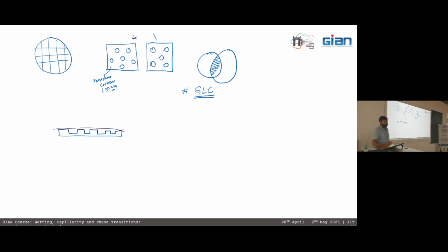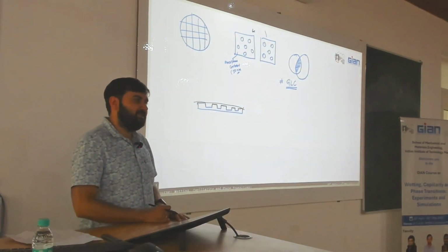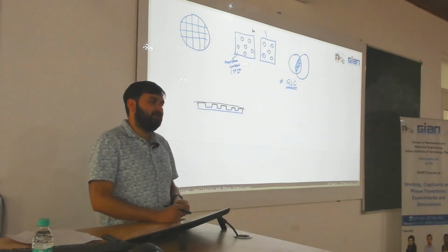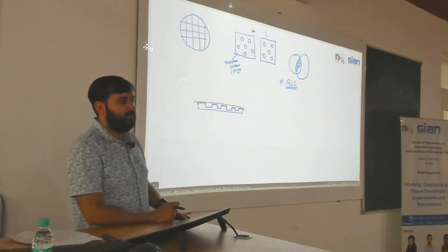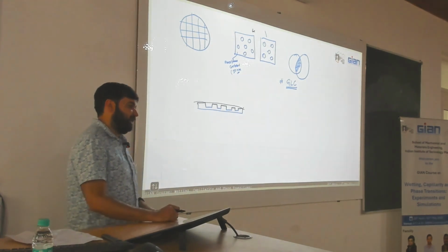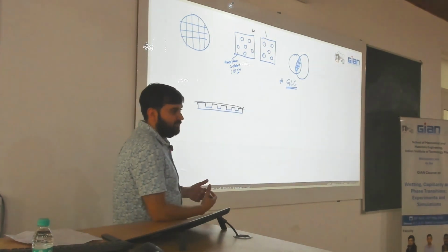So using this, they are able to control where the liquid would be, because in water pockets we don't have any control, but here we have channels. So we can control the liquids, and we can use various MEMS devices, various flow actuators, to even flow liquid through it. So even flow is now possible in liquid cells, where you can adjust the flow rate of reactants and then see how the reaction goes under various conditions.